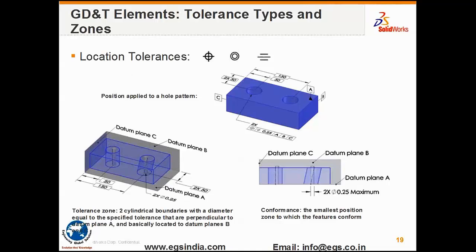Similarly, level 4 is the location tolerances, where you complete the GD&T schema with multiple datums so that the components can be located. This is the highest level of tolerance. The first level contains nothing but the limits dimensioning or fit dimensioning of the sizes, and the highest level is the location. Orientation and form, which happen to be level 3 and level 2, are subsidiary to them or are built inside them. So the highest level is the location, which could either be position tolerance, concentricity or symmetry.